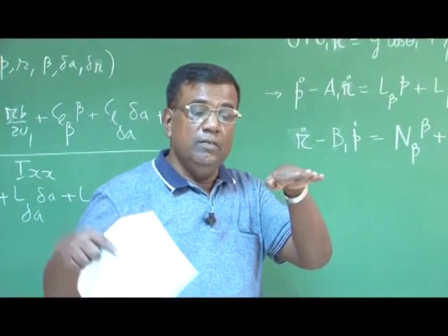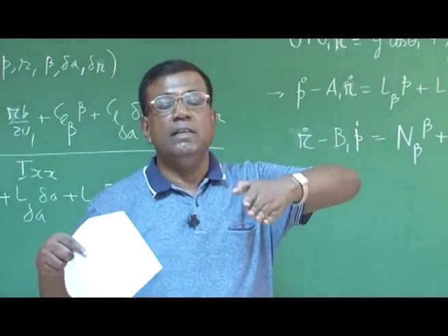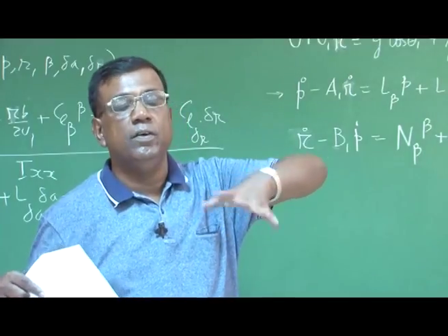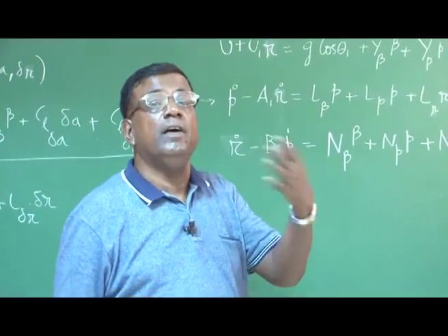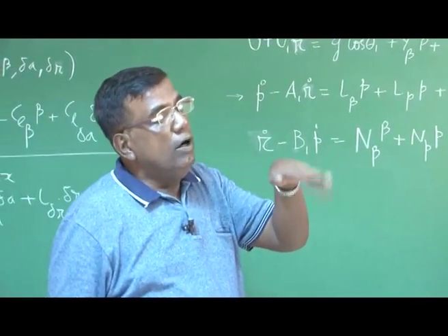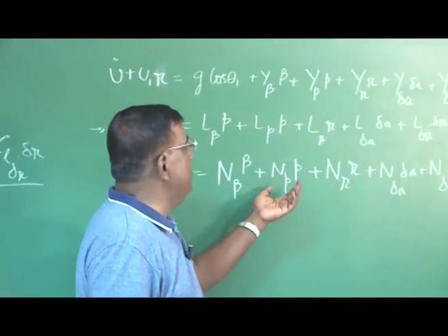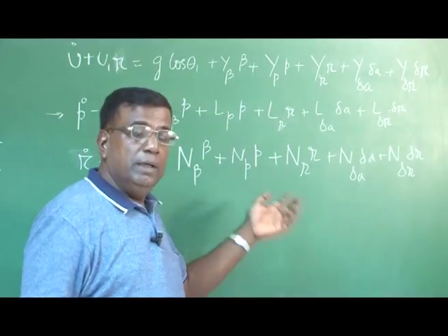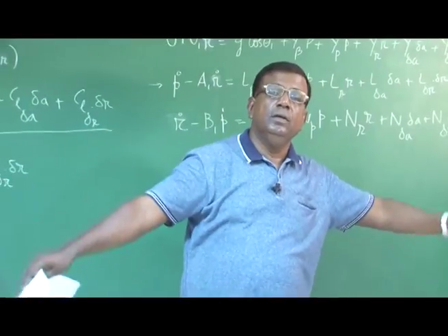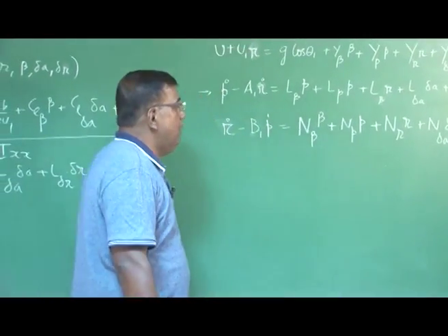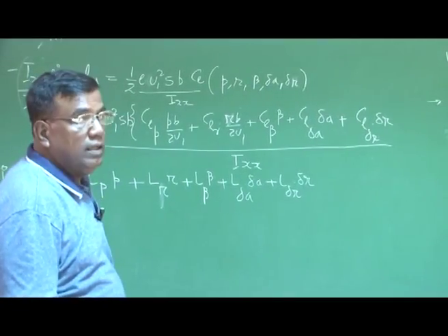Directional stability: if there is a wind like this, it will try to neutralize beta, it will turn like this. So, very, very sensitive, your frequency will go on increasing, right. Like for a longitudinal case, if Cm alpha is more and more, its longitudinal natural frequency goes on increasing. So these are the understandings you should have. NP means damping, roll damping. That is, the moment tries to bank like this, the damping will try to discourage this roll, or it will come faster to the equilibrium once the disturbance is withdrawn.